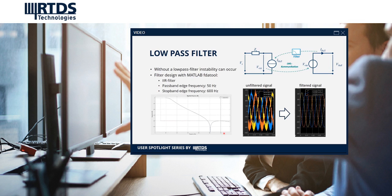Here you can see the magnitude response. You can see that in the passband the attenuation is 0 and then drops to minus 80 dB in the stopband. Here you can see the unfiltered signal with all the noise and harmonics, and after the filtering it is a nice sinusoidal signal.